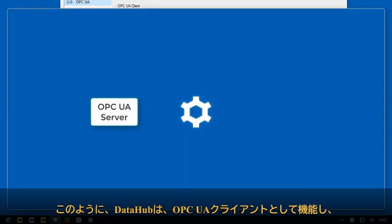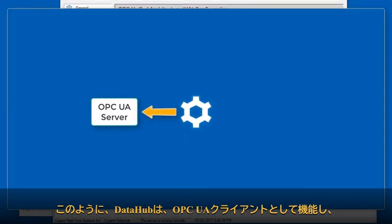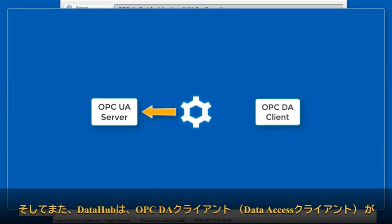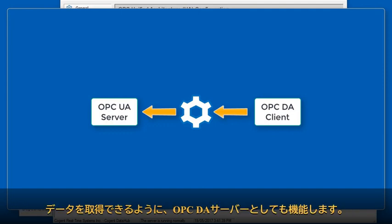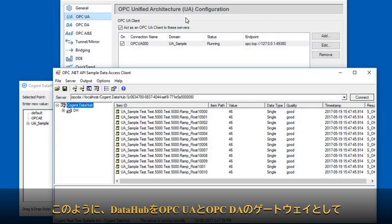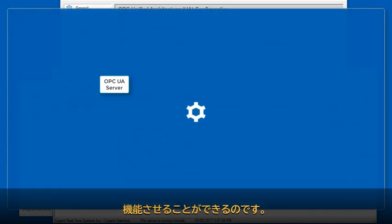So the DataHub acts as an OPC client, or OPC UA client, in order to read the data from the UA server. And it also acts as a DA server so that our data access client, or DA client, can get the data from the DataHub. So that's how the DataHub can act as an OPC UA to DA gateway.